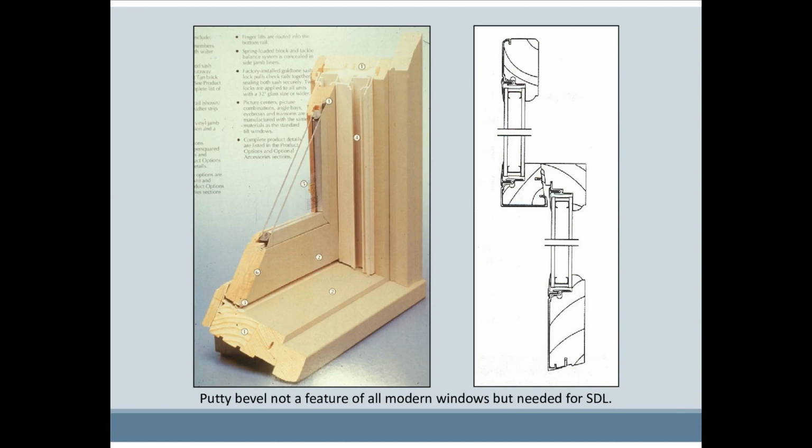While using a wood window to replace a historic wood window will usually result in a better match in most of the details, some modern wood windows have features that are inconsistent with historic windows. This modern window uses a flat glazing clip instead of a three-dimensional stop that approximates the putty line of a historic window. It would not be possible to have a three-dimensional muntin grid with this type of window.